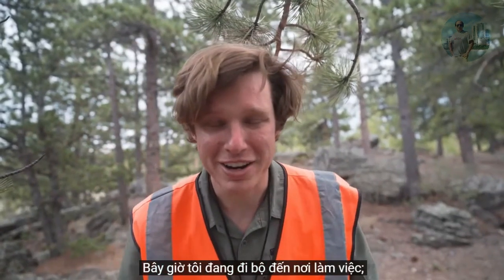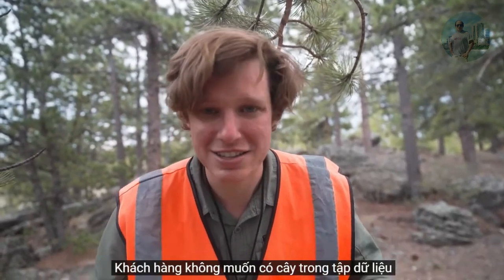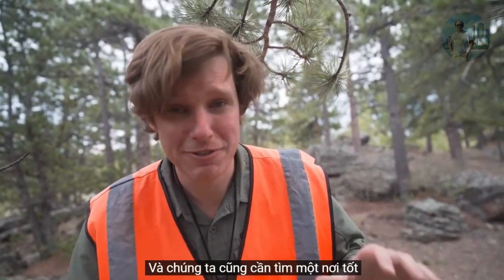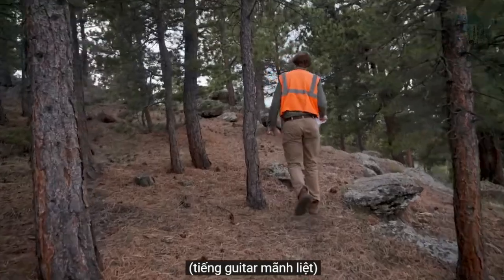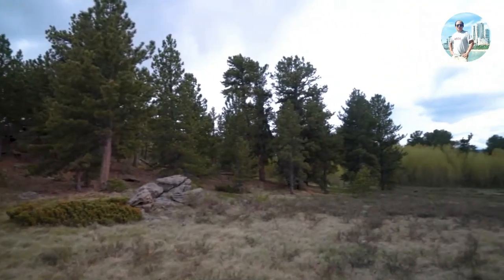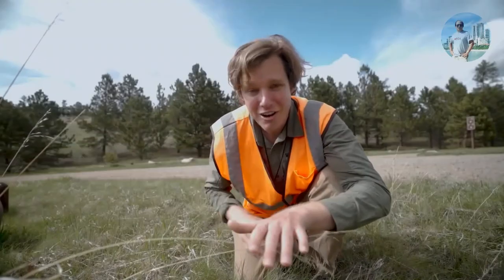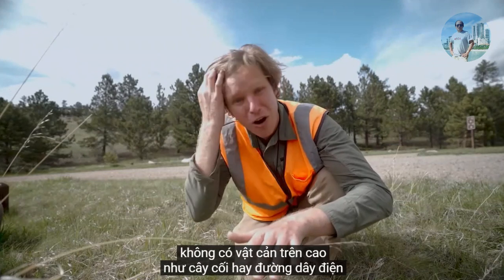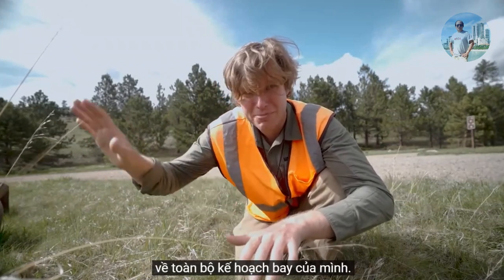We're walking the job site right now. You can see behind me is a lot of trees. The client wants no trees in the data set, so it's just this topographical map of only the ground. And we also need to find a good place to go take off and land from. Alright, this looks like an ideal place to fly from. And what makes this a good place is that there's no overhead obstructions like trees or power lines, and we have a really good view of our whole flight plan.